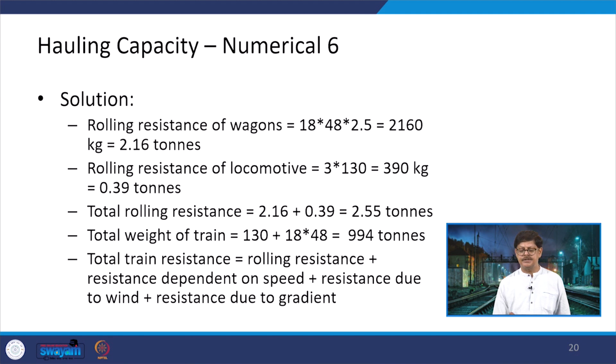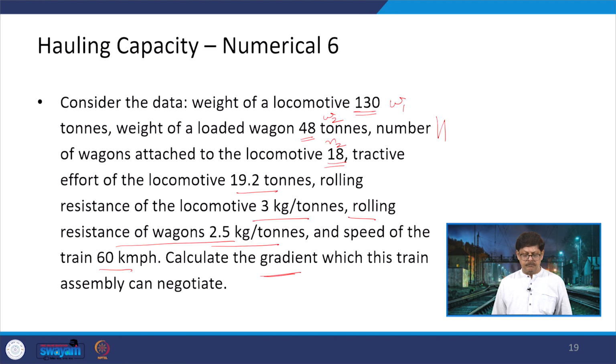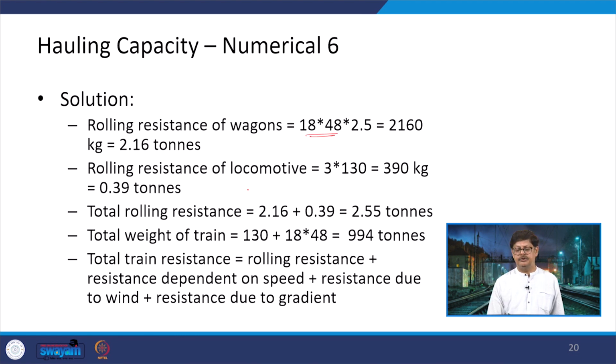So the total load is 18 into 48 multiplied by 2.5, and when we use it here, what we get is 2.16 tons or 2160 kgs.